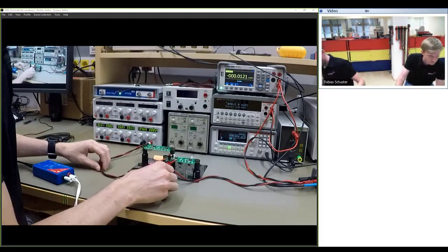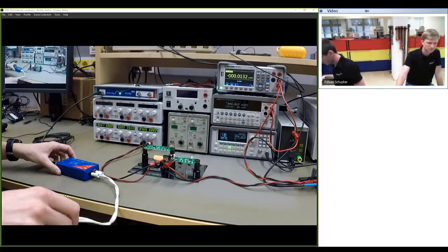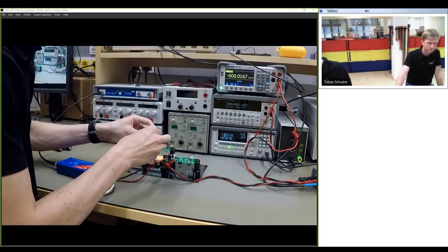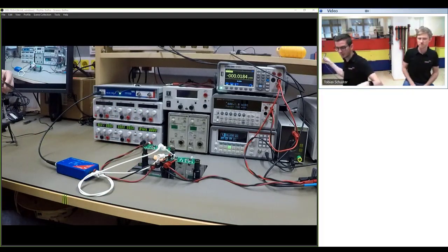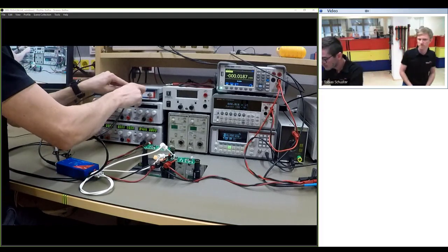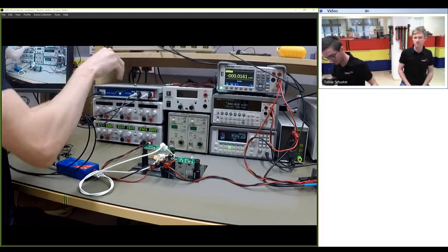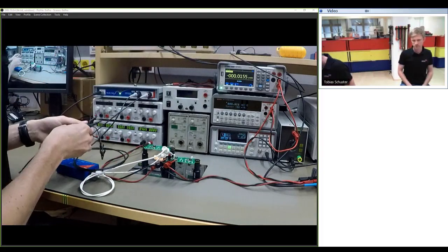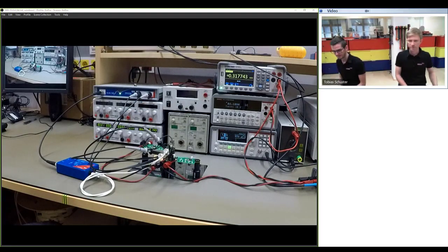And to do the loop gain measurement, now connect the output of the Bode 100 via the injection transformer to our injection resistor, which are these pins here. Now the only thing left I have to do is connect channel 1 and channel 2 of the Bode 100 to the injection resistor as well. That's my last connection. Okay, so now we have set up the system for a loop gain measurement. We have increased the voltage because we know at higher input voltage we shouldn't face an issue,